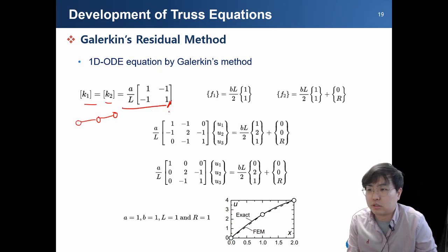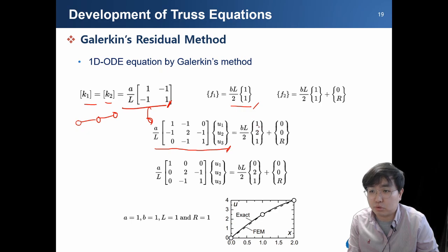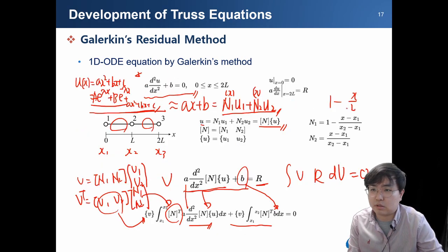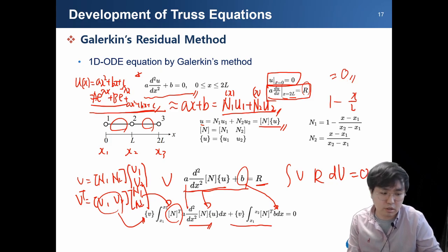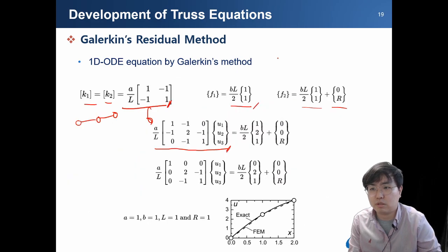So these are the local stiffness matrices, which are then assembled into the global stiffness matrix. The force vector is similarly assembled. This part I did not mention in the previous slide. Here there are some boundary conditions: x at the second point equals a specific value, and the remaining parts, if not mentioned, are maybe equal to 0. This u value is a special boundary condition, similar to a fixed boundary condition of the displacement.